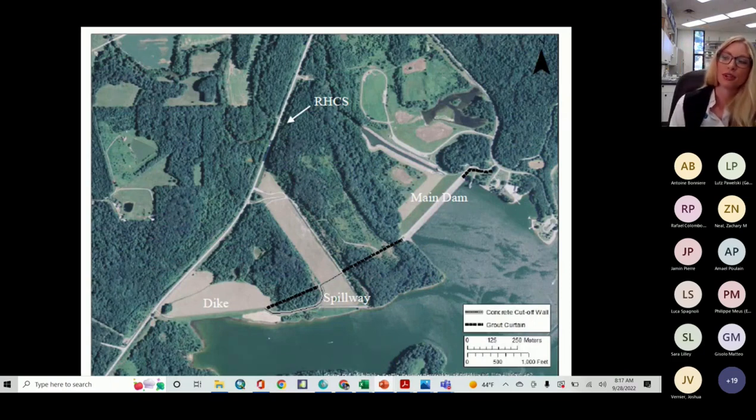Defects including structural weaknesses caused by the undermining of unconsolidated materials as the water is moving through them can cause structural weaknesses in the dam. These result in difficulty or inability to maintain pool stage, which of course could be problematic for navigational waters or recreation or drinking water reservoirs. And of course, dam failure could result in catastrophic flooding, damage to other infrastructure, and hazards to human health and safety.